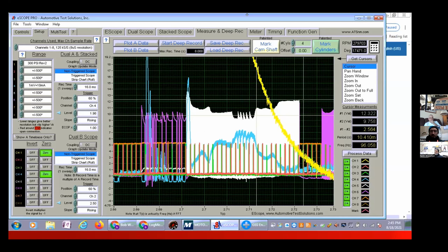And there was nothing wrong with this driver whatsoever before or after the repair. Now, if the guy had kept driving it along like this, I guarantee it would have smoked the driver out of it. But in this case, a motor fixed it, and it didn't need a DME, and it didn't need an eccentric shaft and a sensor, and it didn't need all the other stuff. It didn't need a throttle motor, and it didn't need this, and it didn't need that. And that's the important piece of the discussion we're having today, is the physical ID on the problem, guys.